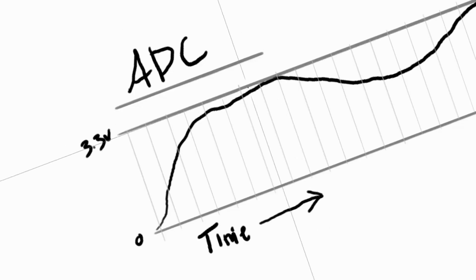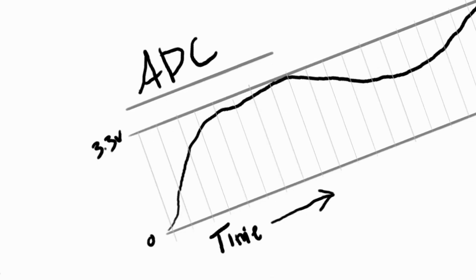You can take that voltage and you convert that to a number that you can use in computation. And you have to think of it in a way that something that you want to sense, like something in the environment, will most likely give you an output in a voltage, and in a voltage between two specific reference voltages from 0 to, let's say, 3.3 volts.